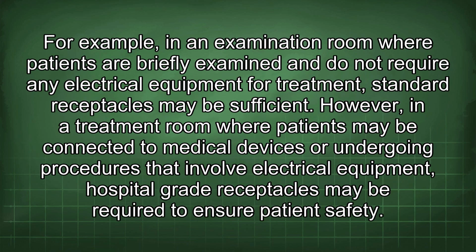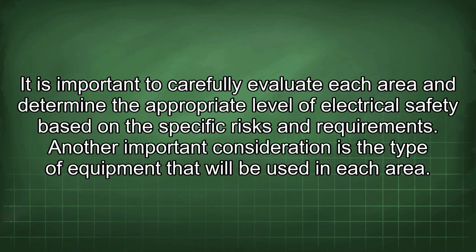For example, in an examination room where patients are briefly examined and do not require any electrical equipment for treatment, standard receptacles may be sufficient. However, in a treatment room where patients may be connected to medical devices or undergoing procedures that involve electrical equipment, hospital-grade receptacles may be required to ensure patient safety. It is important to carefully evaluate each area and determine the appropriate level of electrical safety based on the specific risks and requirements. Another important consideration is the type of equipment that will be used in each area.